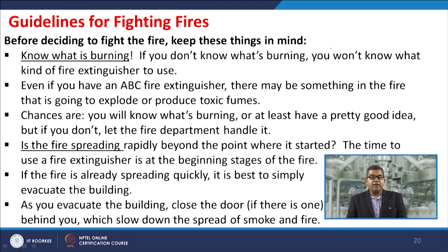Now, before deciding to fight the fire, keep certain things in mind. You must know what is burning. Based on your engineering knowledge, based on the knowledge of your 5 ingredient cup of tea, you must know what is burning. If you do not know what is burning, you will not know what kind of fire extinguisher to use. So, that is why the proper display and proper knowledge of that particular process is essential.